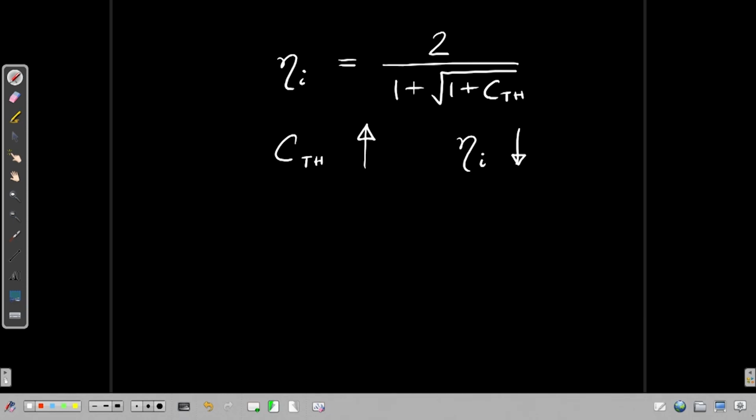That means, when the disk is not producing thrust at all, that condition only will lead to an efficiency of 1. So, for any practical condition where a finite thrust is being generated, there is a value of efficiency which will be less than 1.